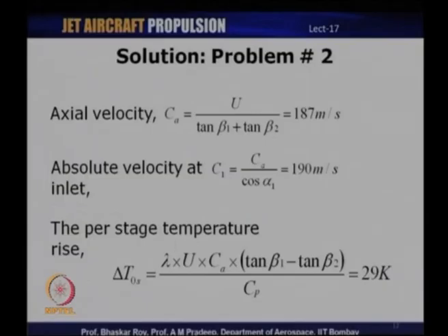So, work done factor is like an efficiency parameter which has been added, basically because if you consider a multi-stage compressor, as we proceed from the inlet of the compressor to the exit of the compressor, I was discussing about annulus losses, that is the growth of boundary layer from the inlet to the exit. That is, there is a boundary layer growth or development taking place from the inlet all the way to the exit, and that means that the effective area of the flow that is available, which is free of the boundary layer, will continuously reduce. That is, the blockage increases as we move from the inlet of the compressor to the exit. There is an increase in blockage as we go from inlet to exit.